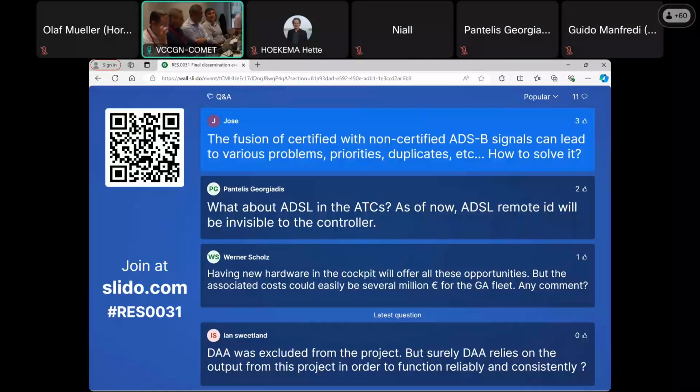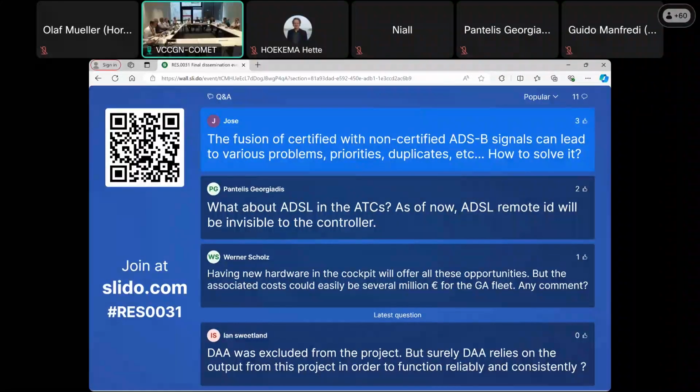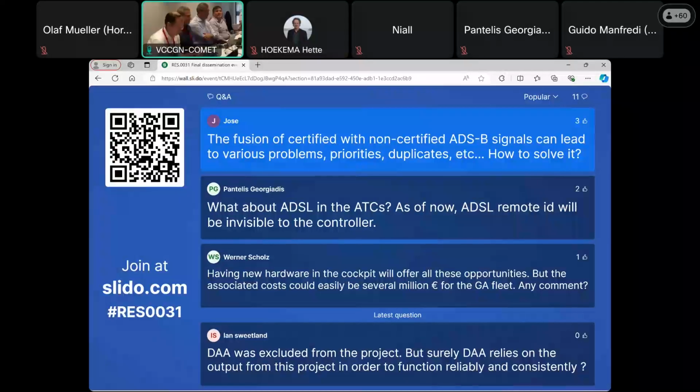You get a hex code there for your aircraft, and the only thing is that in solutions like mobile apps, you often have the problem that you have duplicates because of different transmission paths that are coming into the system, and you have to filter out which it is. So if you have the mobile app in your own aircraft, you can filter out your own device. But if you are sending out more than one transmission path, like 1090 together with FLARM and something else, then others receive different signals of you. That's true. It's still a problem to filter that out, but not with the ADSB signals.